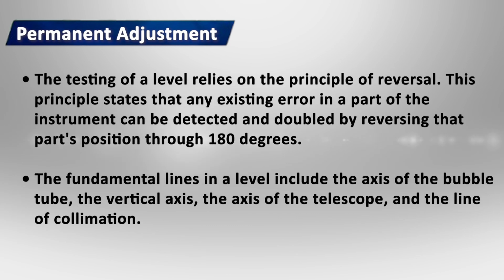The testing of a level relies on the principle of reversal. This principle states that any existing error in a part of the instrument can be detected and doubled by reversing the part's position through 180 degrees.